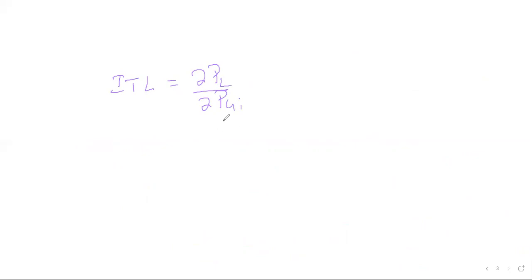So here we discussed the coordination equation. In other words, we write the same equation, that is dCi by dPgi equal to lambda into 1 minus dou PL by dou Pgi, which we got.